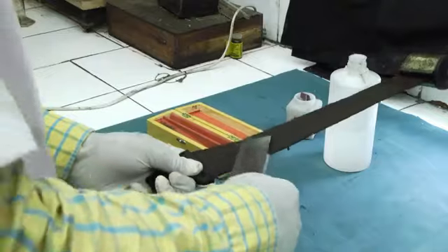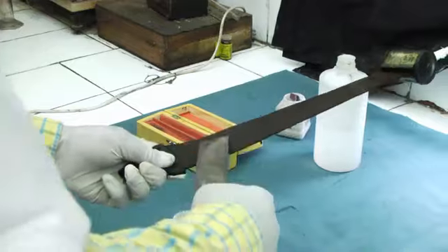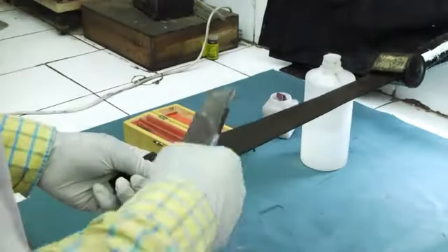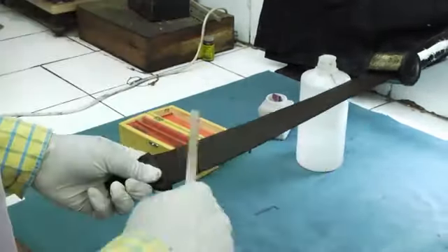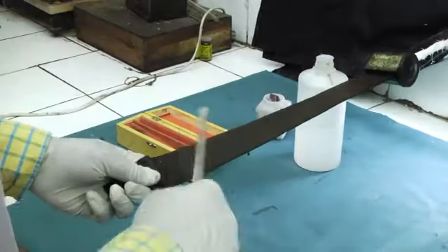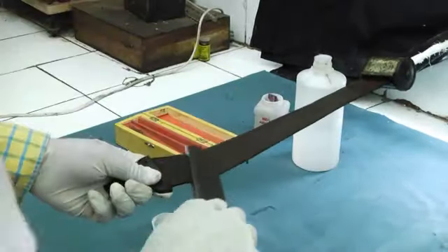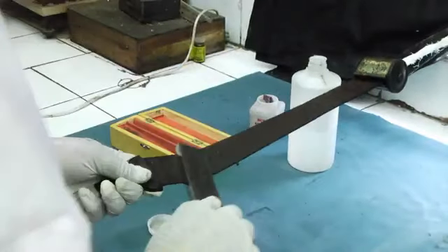Stropping. This is a process of polishing an already fairly sharp edge that may be flexible or rigid. Before use and regularly, strops must be oiled and dressed with fine carborundum powder. The rigid type is a single leather strop stretched over a wooden frame of about 12 by 2 by 2